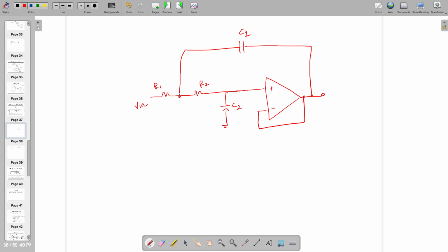So what do the golden rules tell you, Anvesh? Not V out equal to V in: V plus is equal to V minus, and no current flows inside the op amp. Okay, no current inside. So this is just a triangle, right? This only happens when the gain of this amplifier is infinite, and if nothing is written, it means A equals infinity.